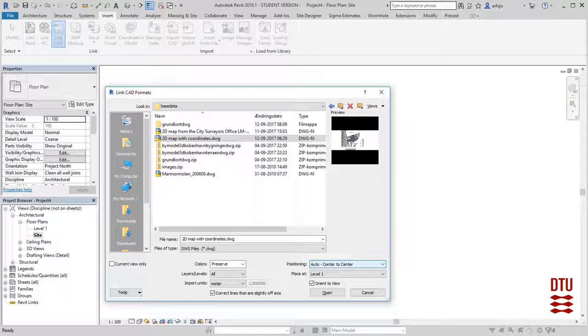and then it will place the center to center anyway. The reason for this is that if you look at the Earth and you see the curve of the Earth, then the precision or the accuracy inside Revit for this curve says that if you are within a mile, then the accuracy would be 1 to a 128 fraction of an inch.